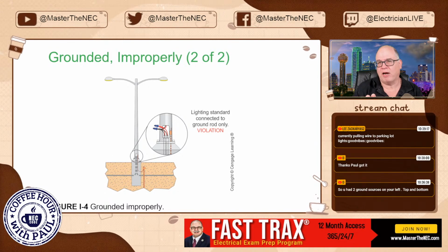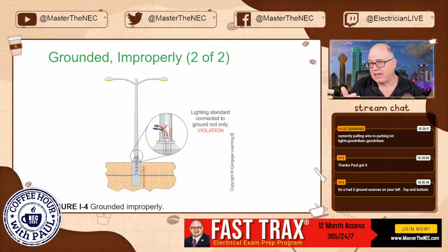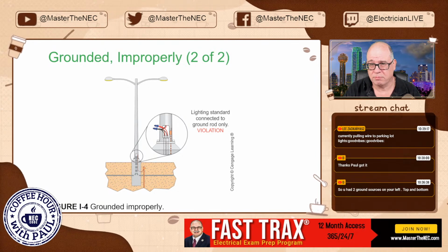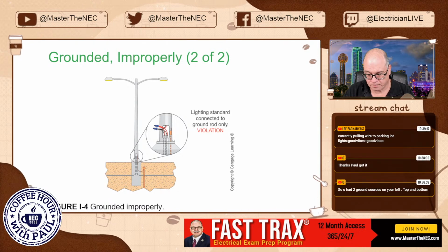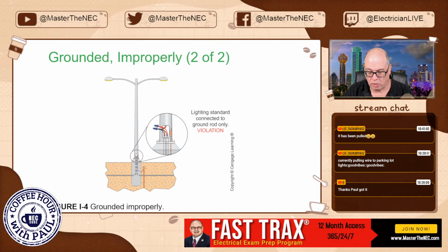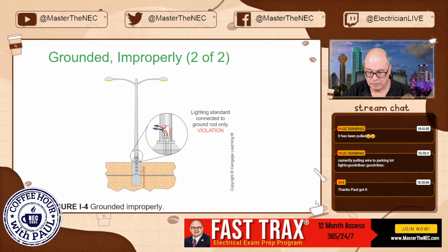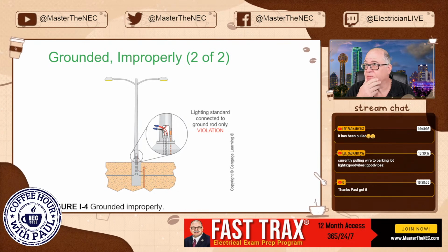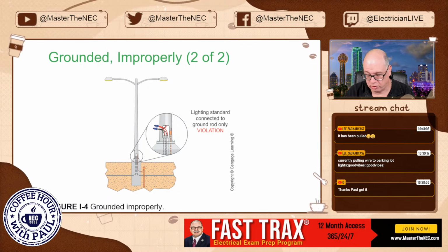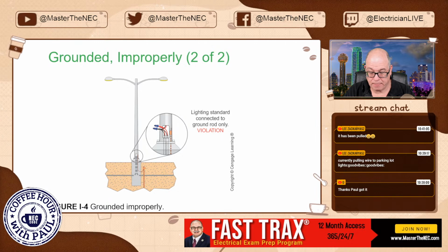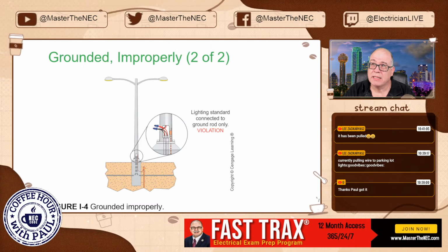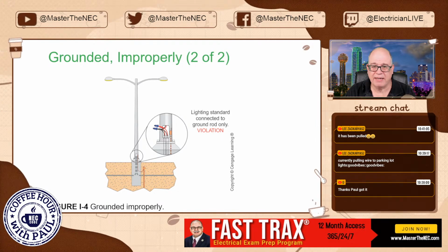If I drove this ground rod and they only have one, and let's say in a perfect world it was 25 ohms, perfect world, okay? So it's 25 ohms at 120 volts, and you're thinking, well, that'll clear an overcurrent protective device.